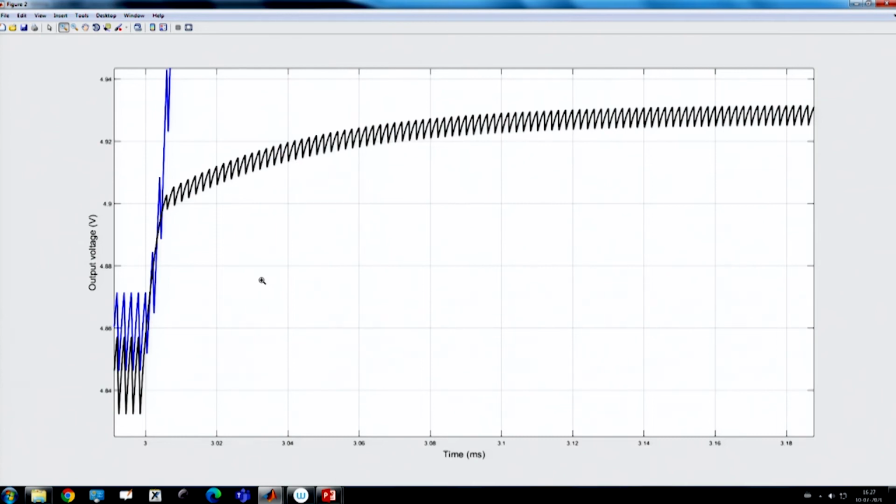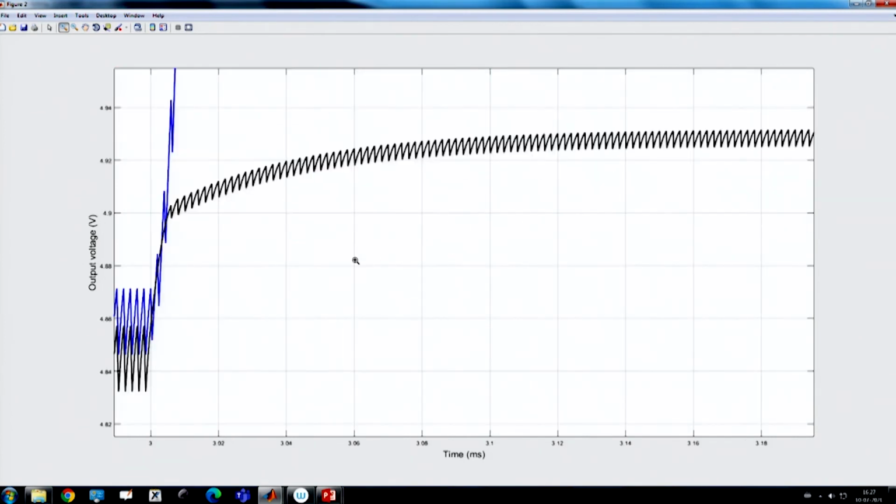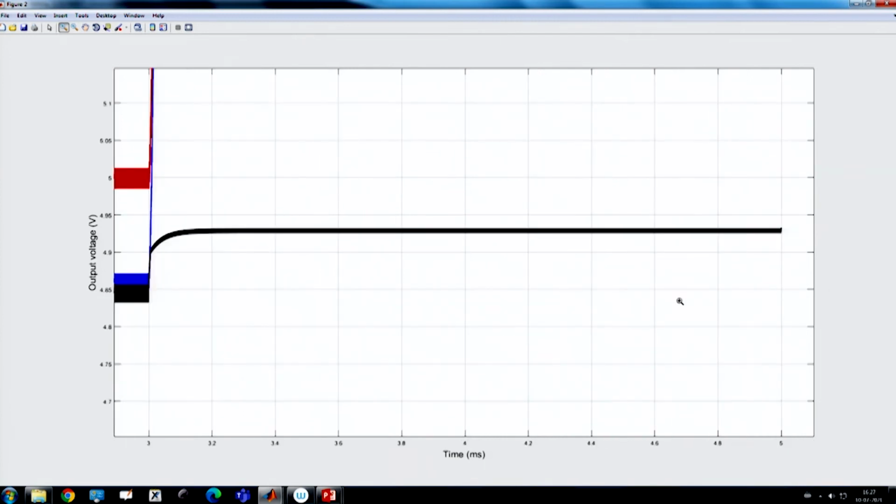So you can also implement average current control. Because the inductor is on the input side, we will see in a subsequent lecture that in a boost converter, even with current mode control, the audio susceptibility has a first order effect, and that is why it is slowly rising and reaching 0. But still, we can significantly reduce the effect of the disturbance. That means we can achieve very nice performance from here.